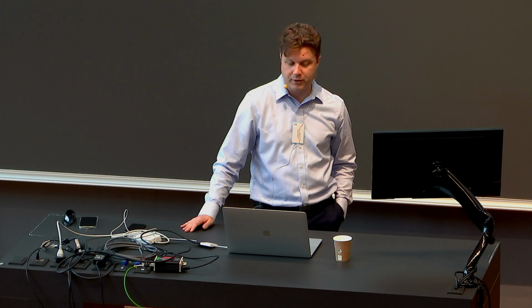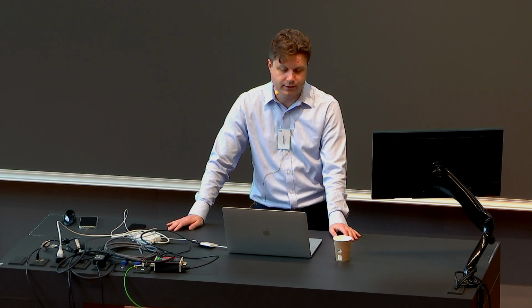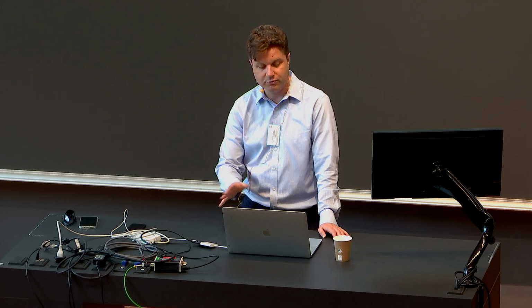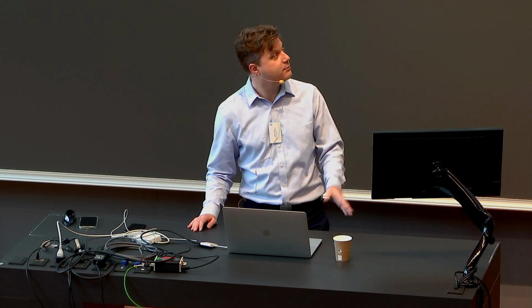When you're done, the print_summary function, which works on the network data, also works on the results data. So you get some results back. It includes things like the status of the solver, what the objective function was. But most often, you're going to want to look at the solution data. So that's the information about what the power flow was that was found by the solver. And you can use print_summary to print that solution data. And I suspect it's pretty self-explanatory.